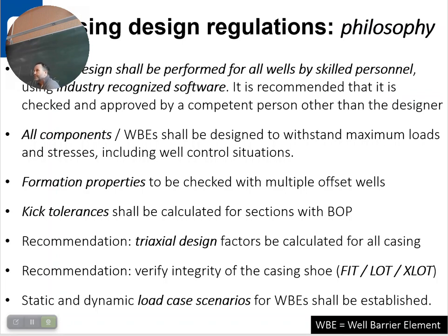That's what it wants to do. What happens if you don't bleed off at the top? It doesn't expand, right? And what happens then? It keeps the pressure. So it's going to have 300 bar going here, like this. And it goes up to the top, right? So your mud profile, let's say that you have 1.5 mud, it's going to look like this. After the gas bubble has come to the top, you have to move to 300 bar, and you have to do this.